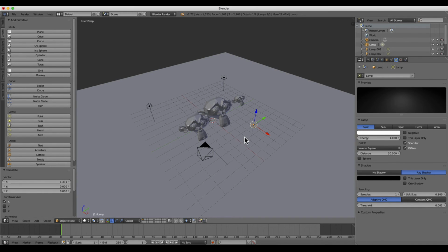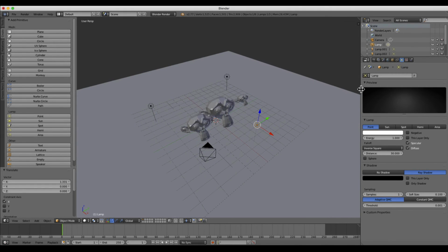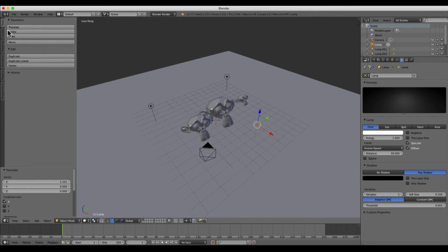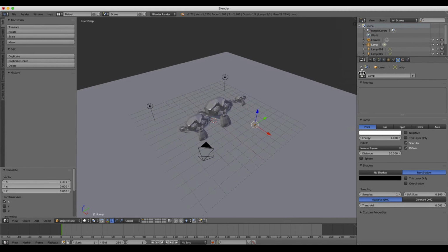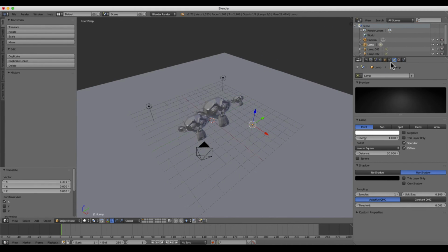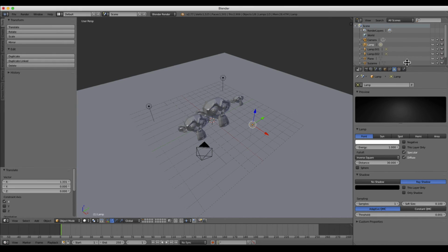So one last thing I want to leave you with before we jump out of this tutorial is how to move the windows around in the panels when you start getting into Blender and playing around. Sometimes you don't want the default layout to be the way it is. Sometimes you want to play around with things. And so what you can do with any of these panels that have an outline with black right here is you'll see the icon change to a split icon like this, and that will mean that you can left click and drag to change the size of this panel. You can do the same thing here, just like that.